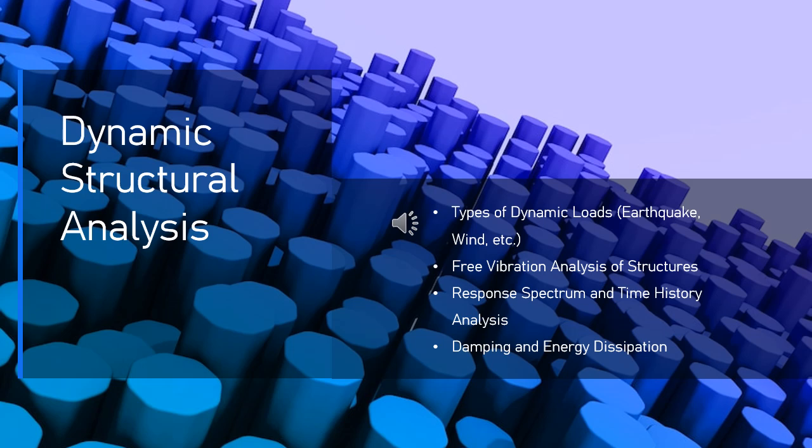1. Model the structure. Divide the structure into simpler components, finite elements, each with its own mass and stiffness properties. 2. Solve for modes. Use the mass and stiffness matrices to solve the eigenvalue problem and obtain the natural frequencies and mode shapes. 3. Interpret the modes.